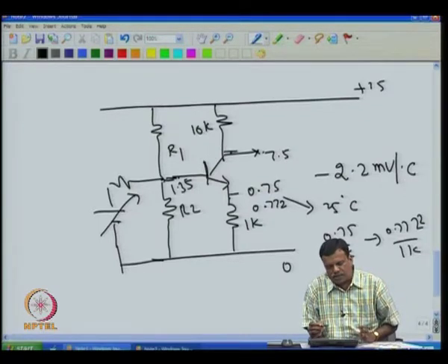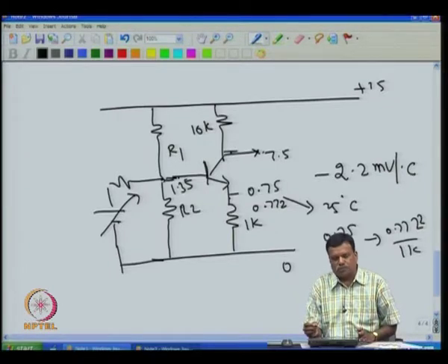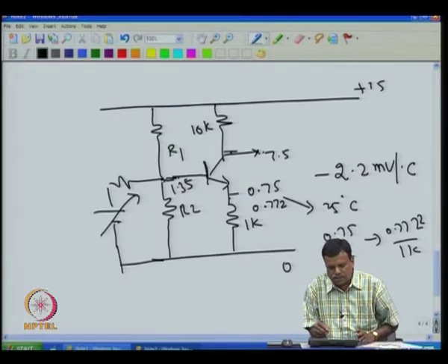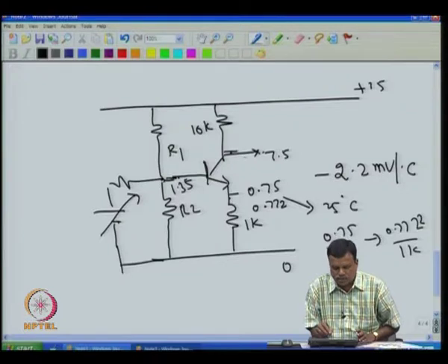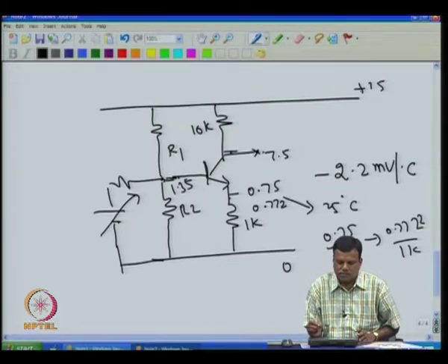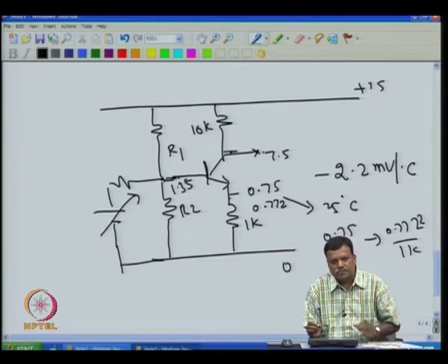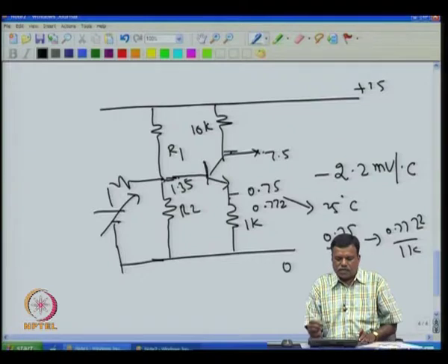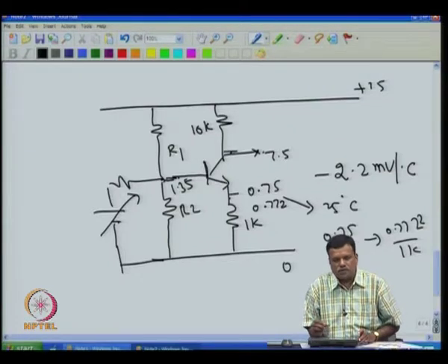The same thing was there at that time with vacuum tubes as well. When they were using vacuum tubes, amplifying a DC was a problem because of this so-called change, which we call a drift. The drift of the voltage at this point due to temperature and the power supply is a major issue. So, various attempts were made to solve this issue.